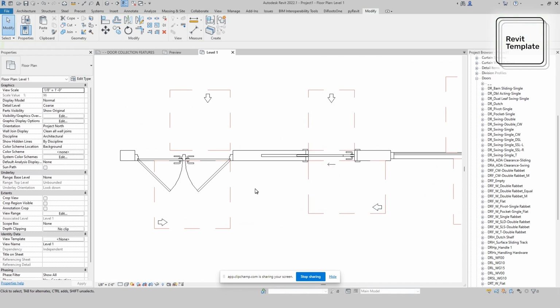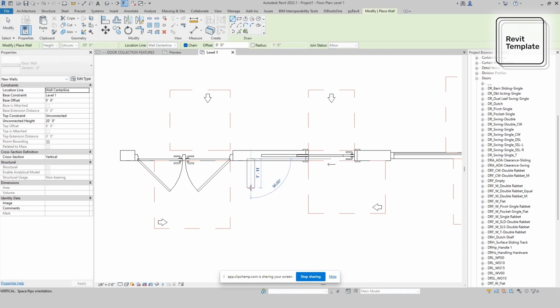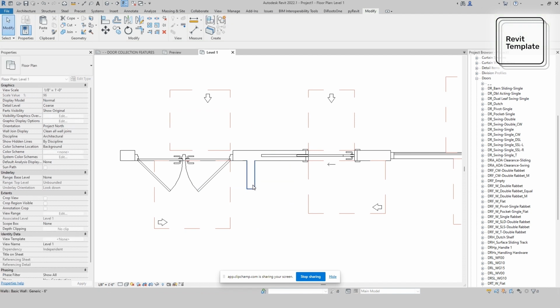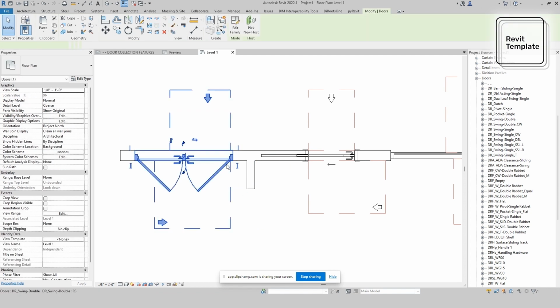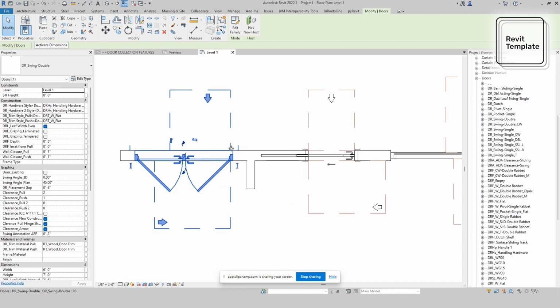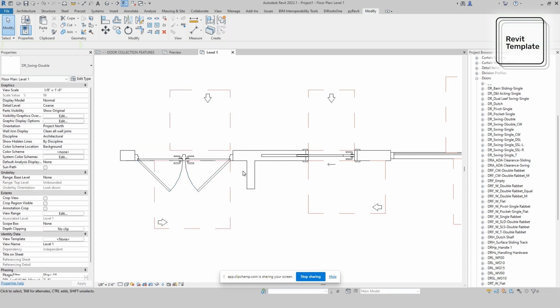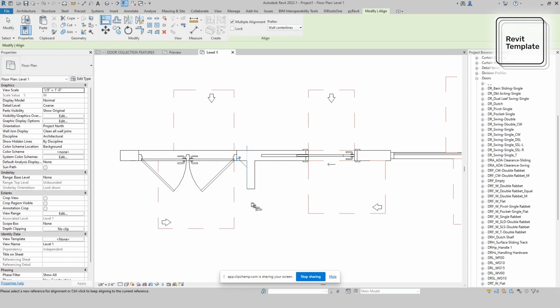Lastly, our collection incorporates a door placement alignment feature, so users can know when their doors are aligned at a fixed distance every single time without needing to break out the dimension tool. This is indicated by these invisible lines that are only visible when the family is selected and are adjustable at this parameter here. So users can easily set it to 4 inches, 10 inches, and in doing so, users can easily align the dimension to the wall and have it be perfect every single time without having to adjust anything.